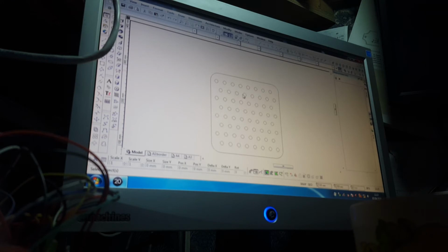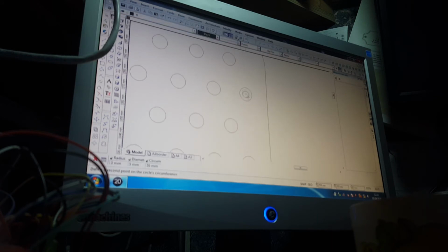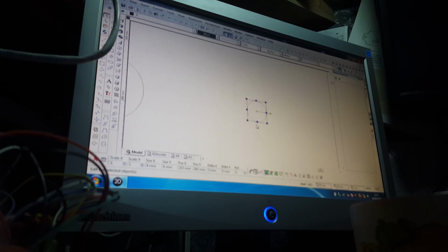What I'll do is I think I'll, from that point there, I think I'll just put a little hole in instead for fixing the lug hole. Say 8 diameter. Say we're screwing this to something. Let's go 4 diameter. I'll delete those circles. Don't want them. In fact, I think I'll make a slot.